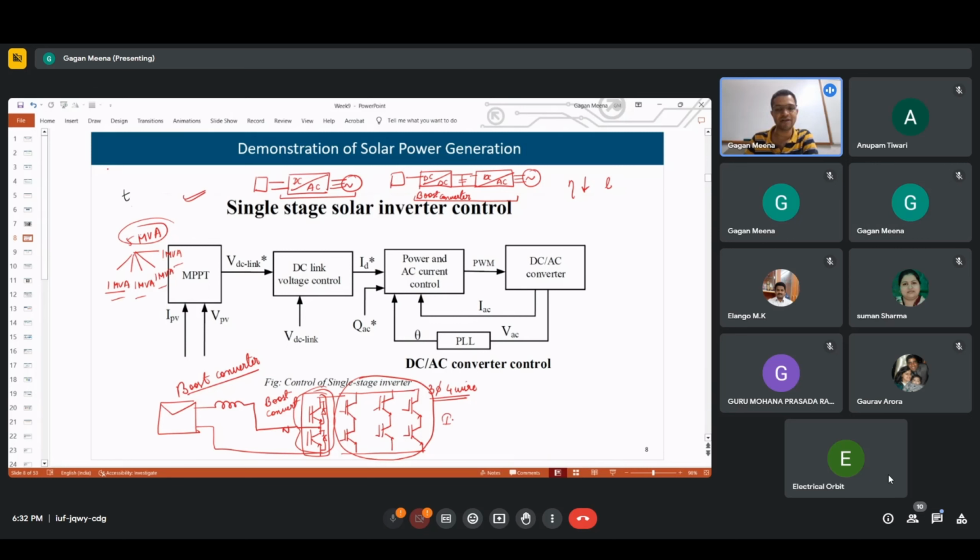Because electric vehicles are increasing, we need to develop standards for charging infrastructure. Different countries have different standards, and India has also adopted several standards. There are 4 modes for EV charging. One is mode 1, which is direct connection to the socket. At home we have this 15 ampere circuit. We can directly connect those EV chargers. Those are simple EV chargers.